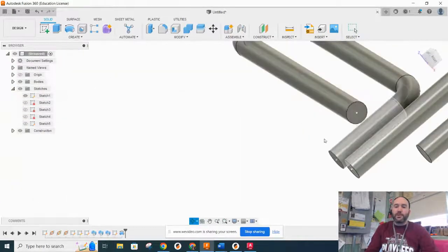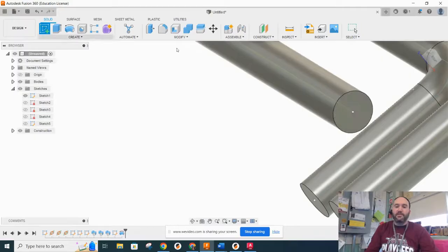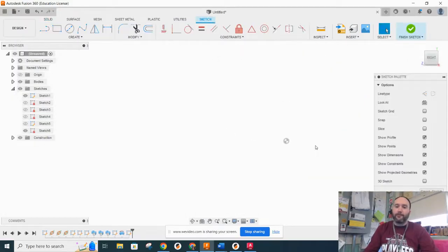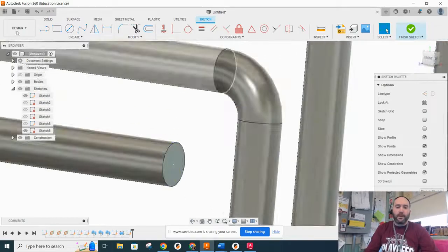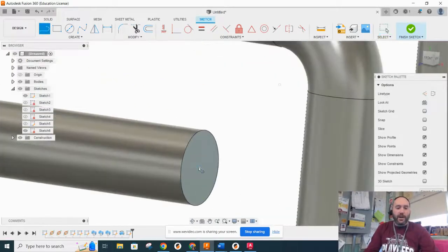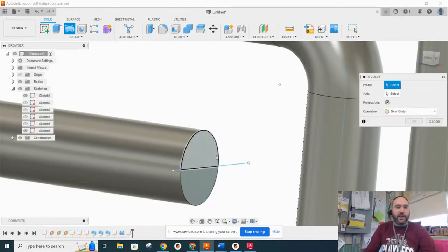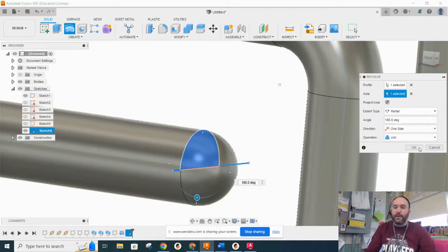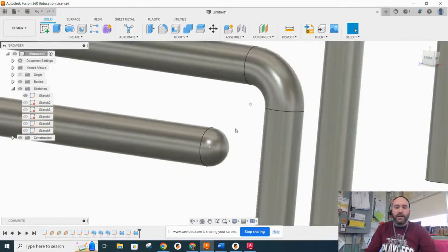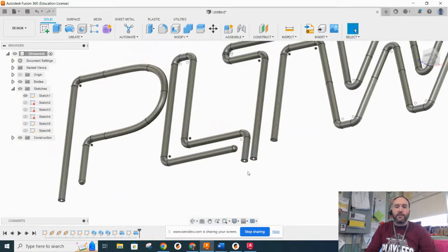So on this one, that's my transformer end. This is my neon end. So I'm going to go ahead and create a sketch here. And once again, I'm going to just track off the center, draw my line through. I can finish the sketch, and now I can do a revolve of this side, select my axis, pick the axis, and that needs to be a join. It needs to be 180 degrees, and we're going to join it just like so.